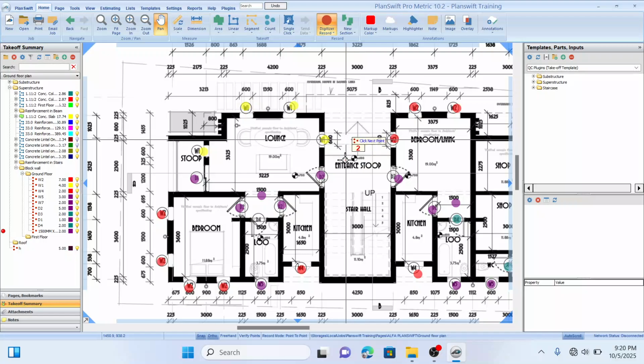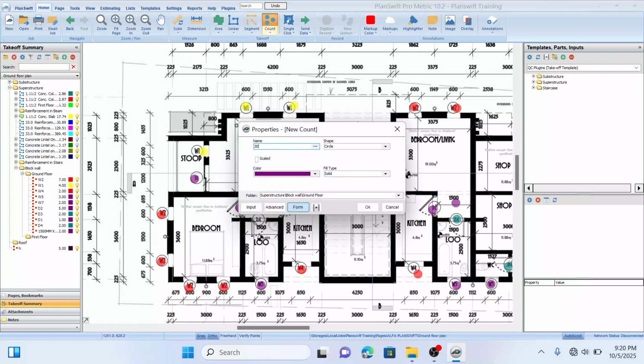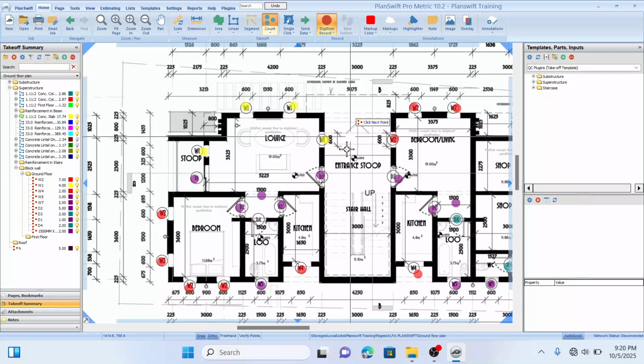The other opening we have here is the opening to the stair hall. I think this place is the entrance top. This is the opening to this stair hall area. The length of this opening is 3 meters. Let's make use of the standard height 2.1. So that will be 3 meters by 2.1. So we have one of that here.